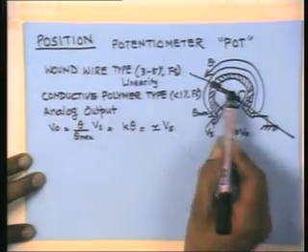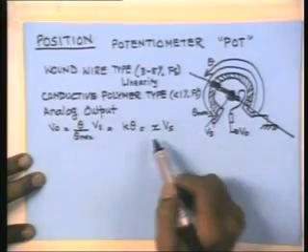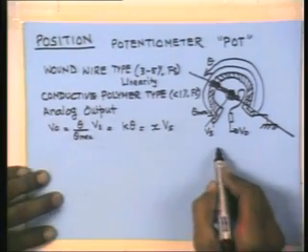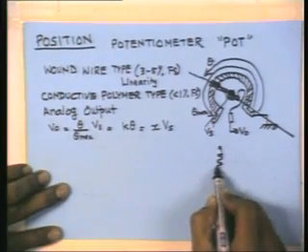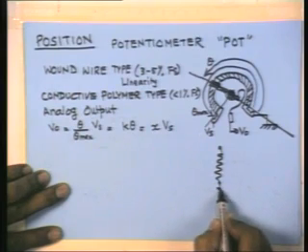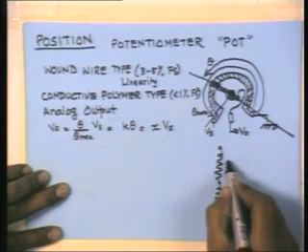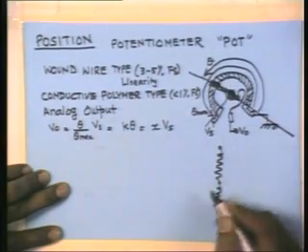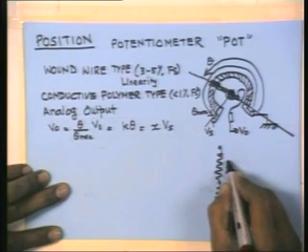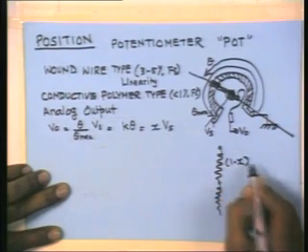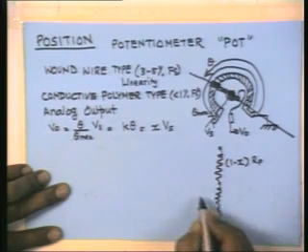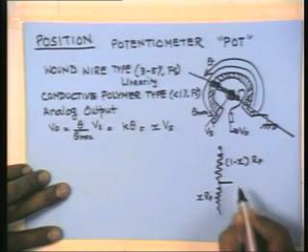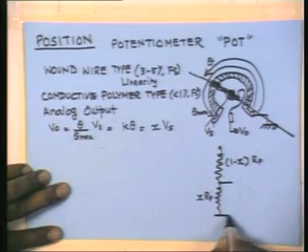So depending on how far it's traveled along the resistor, you can have the voltage directly dependent on that. So basically the effective circuit that we have here is a voltage divider circuit. If the total resistance of the film here is R potentiometer, Rp, then I have (1 minus x) times Rp here and x times Rp here, and then I am taking the output from here, and typically when I am trying to measure the output,